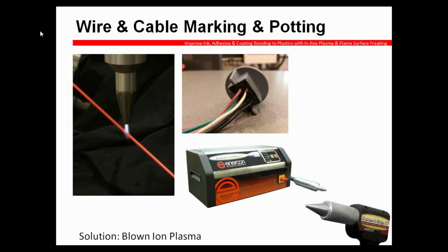It's important that the ink stays adhered through installation. You don't want that ink rubbing off and then the assembly team looking at it and going, well, where does this go? Yeah, it might be a different color, but we're not really sure what exactly this wire cable is intended for. So that industry is becoming higher and higher demand that ink stays adhered. It is a less expensive alternative to laser marking. Laser marking can be very expensive, if any of you have gotten into that, so we do recommend considering plasma if you have that challenge.